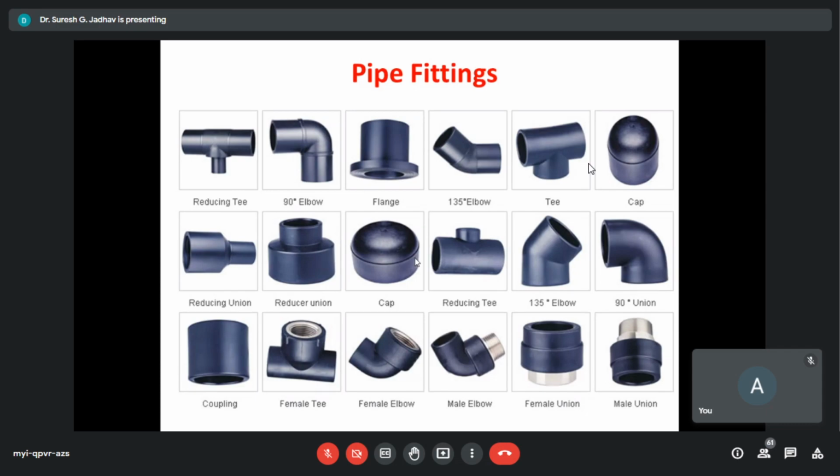And the male end fits into the coupling. See here coupling. So here you can fix the bushings. And the smaller pipe is then screwed on the other end, into the female end, and the smaller connection may be tapped eccentrically to permit a free drainage of water.